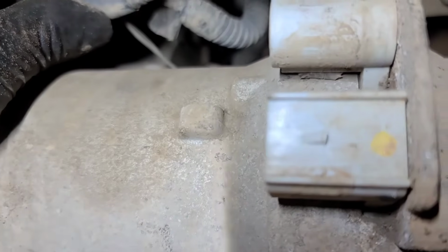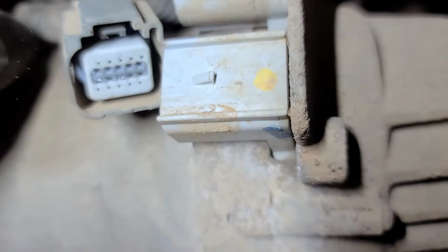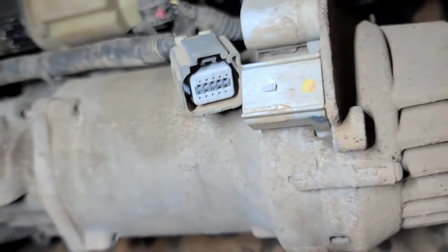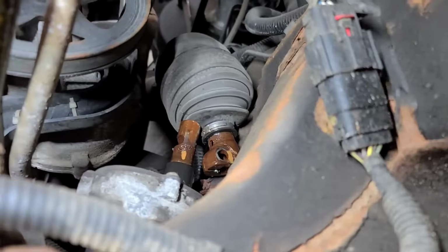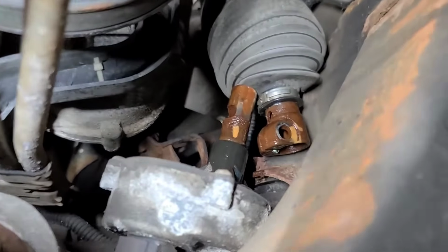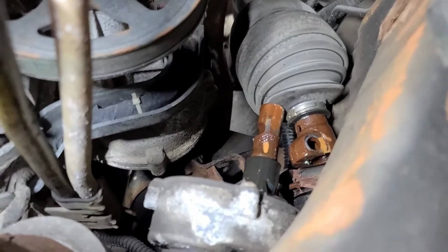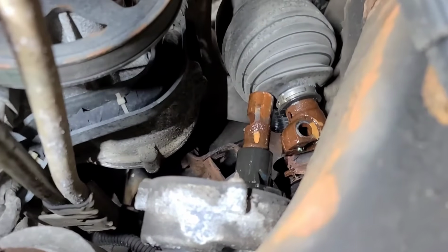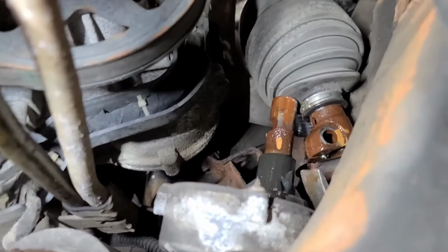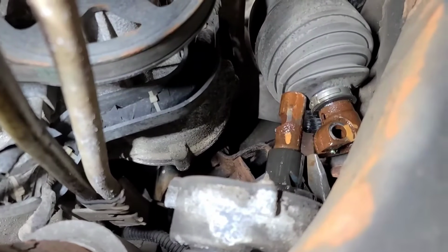Looks like a T20 or T25. Maybe if I disconnect the four-wheel drive actuator, there'll be more room to get at it. So I've disconnected the steering shaft universal joint, and you can release it, spray with some penetrating fluid, and then you can put a pinch bar up through, where did I have it? Up through here, like so, and tap the coupler off.